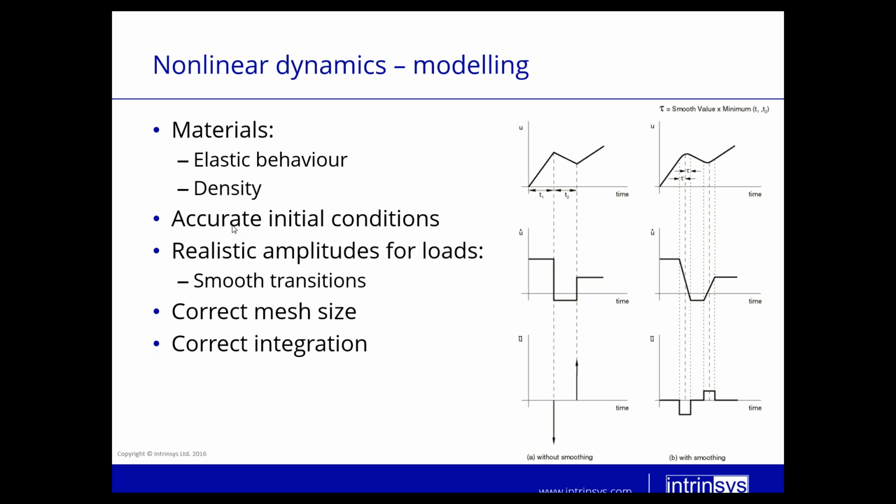We also have to use accurate initial conditions if we are running a time accurate analysis. For example, if we don't set initial speeds or accelerations right, then we can end up with a large discontinuity at the beginning of the model, which could cause very high stresses and that would definitely give us wrong results.